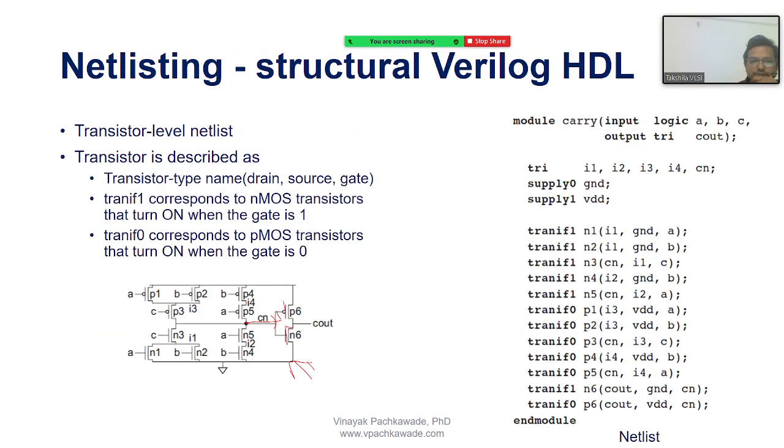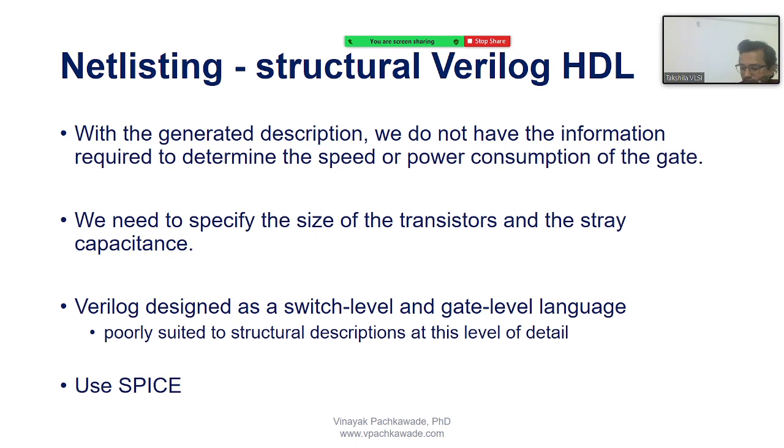There will be no effect of inductance, or it's not considered? Well, at low frequency it is not pretty much a concern. At high frequency, there are some effects called antenna effect, electromagnetic effect, and all that. So in our understanding for now, in this specific course, we'll say R and C.